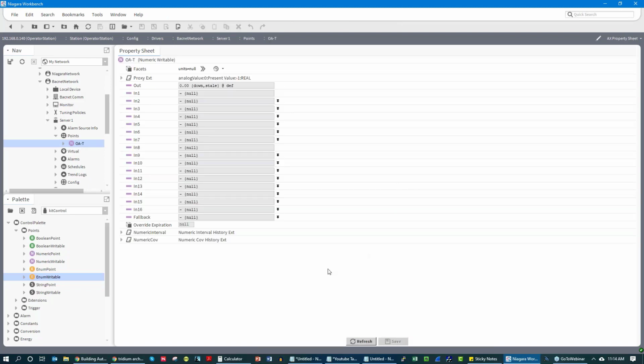And this is a BACnet logical point that is representing a physical point in the field controller. Now, I know that probably confused a couple of you, a logical point that is representing a physical point in the controller. But that's how a lot of these building automation systems work: you have these supervisory devices and you have these field trunks that connect to field controllers. And then inside the field controllers, you have physical points, like in this case, outdoor air temp.